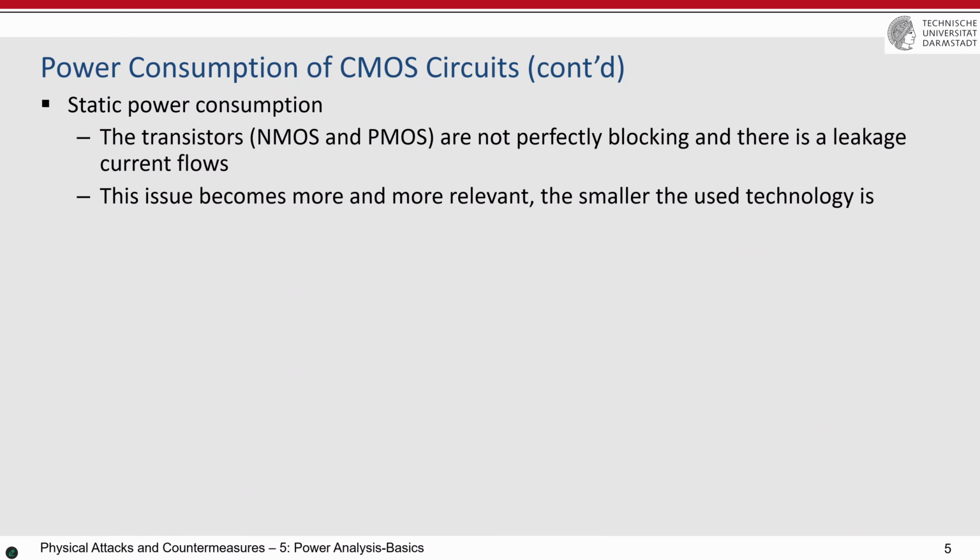When the technology becomes smaller, as I explained, 65 nanometer, 14 nanometer technology, and then 28 nanometer, 16 nanometer, 9 nanometer, 6 nanometer, and so on. When the technology scales and gets smaller, the amount of static power consumption becomes a bit higher. It's not dramatic. It's not like the static power consumption is now 10 times larger, but it became larger and larger.